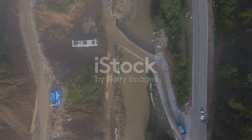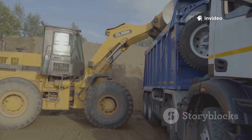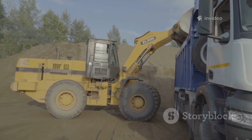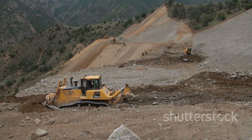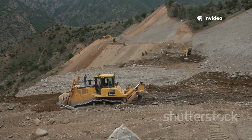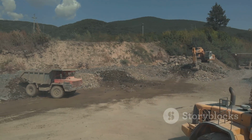Let's see the mass haul diagram in action. Imagine a 1-mile stretch of new highway. The diagram shows a deficit of 50,000 cubic yards, so the contractor knows to secure a borrow pit before work starts. Next, the diagram highlights a balanced section. 200,000 cubic yards can be moved from a hill to a nearby valley, all within free haul. This becomes the first, most efficient phase of earthwork.